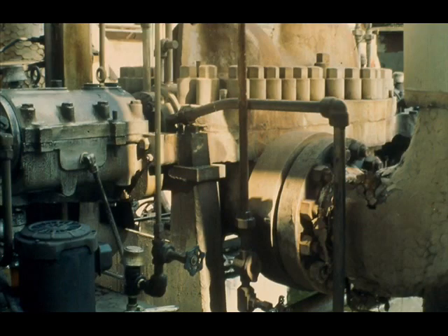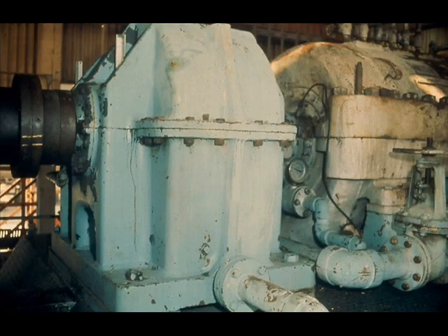In some pumps, as is the case with this one shown here, the horizontal forces are such that a thrust bearing is required to equalize these forces. Gearboxes, which sometimes are designed to produce no horizontal thrust of their own, may require thrust bearings to resist thrust imposed on them by the machines they are driving.